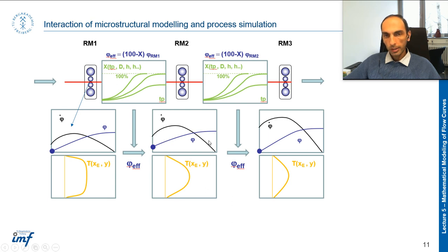However, you can see a sharper peak in strain rate also, and for temperature also you can see that it's sharper compared to the previous rolling stage. Okay, so on a bigger scale, for example the rolling stage, you can understand the effect of strain rate and temperature, how they change during the process, and of course how they will affect the flow stress.